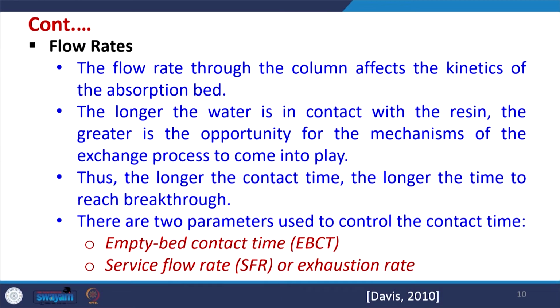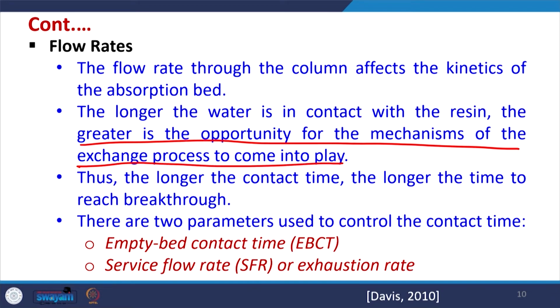The longer the water is in contact with the resin, the greater is the opportunity for the mechanism of the ion exchange process to come into play. That is why the flow rate becomes a very important parameter. The longer the contact time, the longer the time to reach breakthrough. That means we can treat more volume of water if we have lower flow rates, and still the bed capacity is the same.